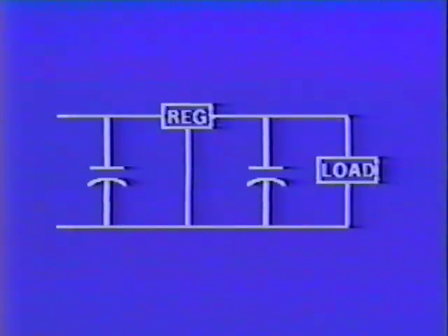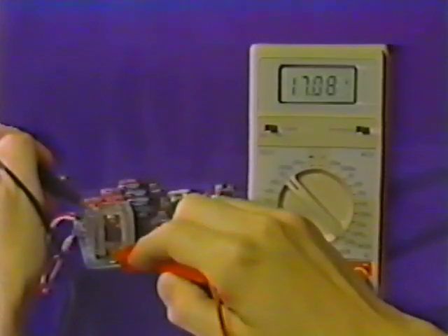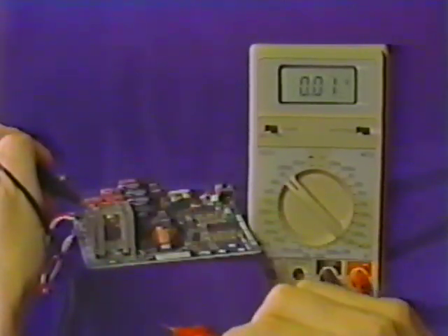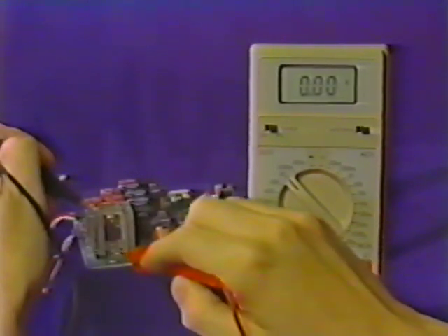Low voltage problems in the regulator section should not be overlooked. If the zener or its resistor opens, the voltage produced can be higher or lower than the desired output. If a 3-terminal regulator opens, a low voltage condition can occur. Testing a 3-terminal regulator is as simple as checking for proper input and output voltages.